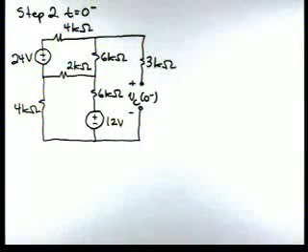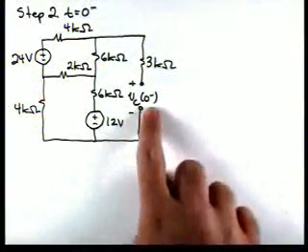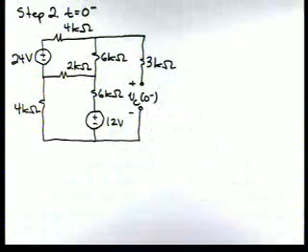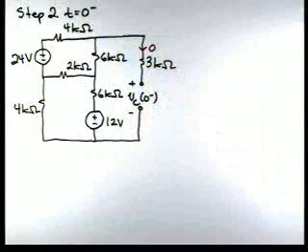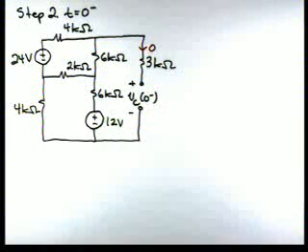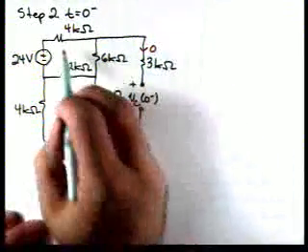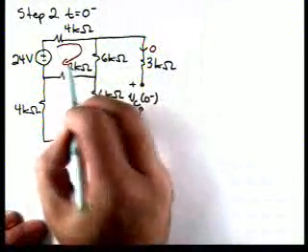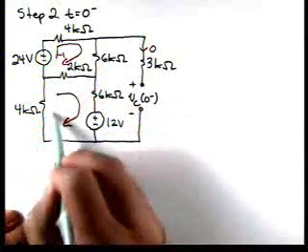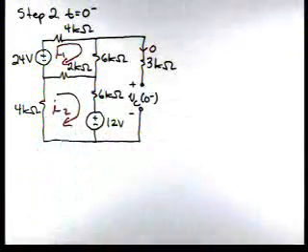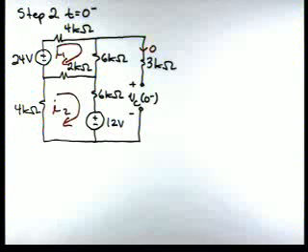So here's our circuit. We've assumed steady state, so we replace the capacitor with an open. So we know, for instance, the current here is 0. Now we need to find that voltage. Here we may as well use mesh analysis. So I'm going to define two mesh currents, I1 and I2, and now let's write mesh equations.